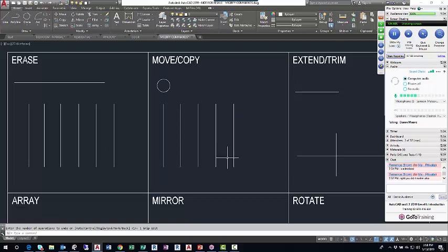I'm only going to add one thing. I'm going to add the move button. It won't look any different. Left click circle, left click move. And it says left click your base point. I don't talk like this, you don't talk like this, but the base point is the center. Where do you want to start this action? I want to start it at the center. Left click the center, and then specify second point, left click the destination or the end point.